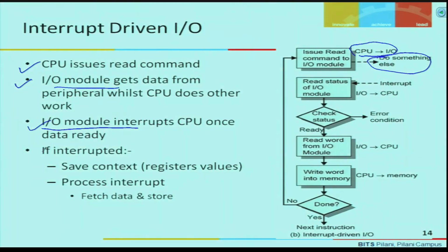Now, once the processor is interrupted and gets that interrupt signal, it has to stop. Then the processor has to save the context of whatever program it is currently running. So the current PC value and other processor registers, which may hold temporary results computed for that program, have to be saved at some location so that they can be restored after finishing this I/O operation.